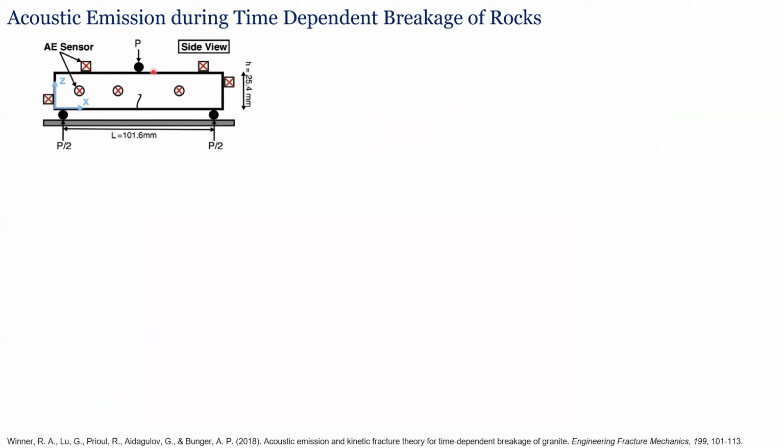You have a set of supports, you ramp up the load P, and you ramp it up until the rock breaks. And if you look at the guidelines for these types of tests, both in rock and concrete, kind of buried in there, there's this sense of loading rate and bounds on loading rate. And if you ask yourself why, it is because rocks are time dependent in how they break, even though we often don't think about that.